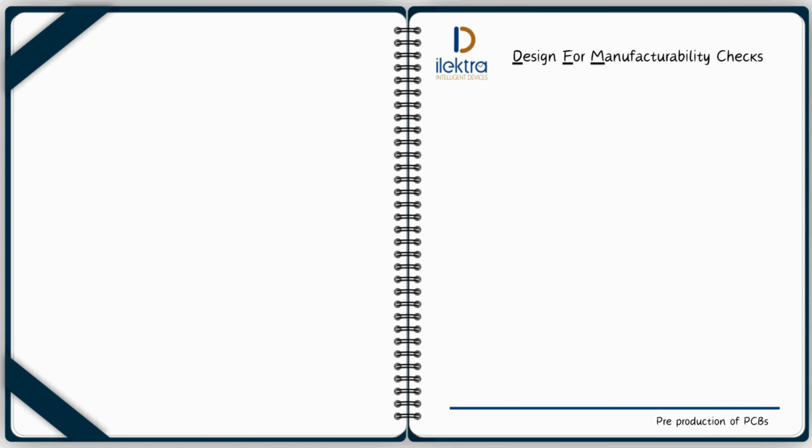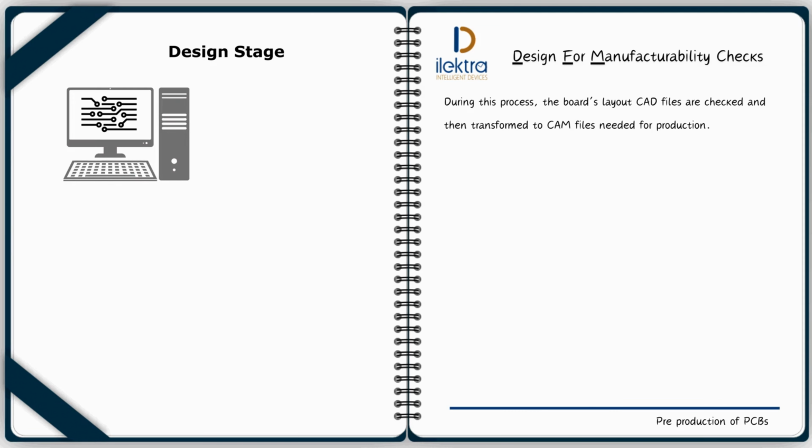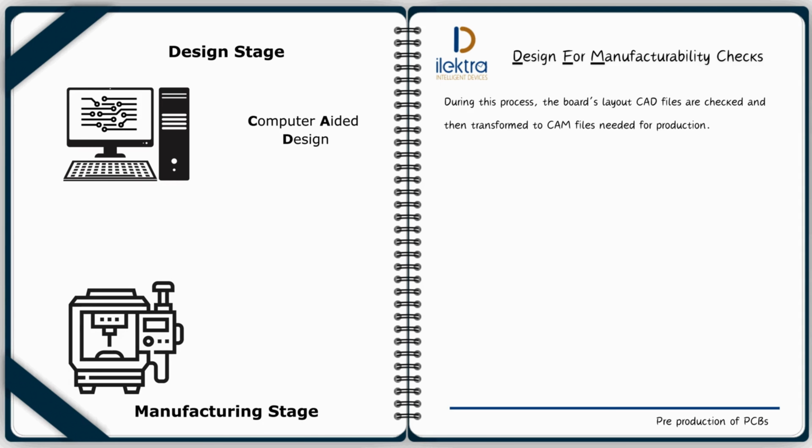The first step in the manufacturing process is the most important one. During this process, the board's layout CAD files are checked and then transformed to CAM files needed for production. In the PCB design stage, the engineers create the circuit schematic and PCB layout of each layer on a CAD software. Those CAD files are not understood by production machines and are mostly useless to the manufacturer.